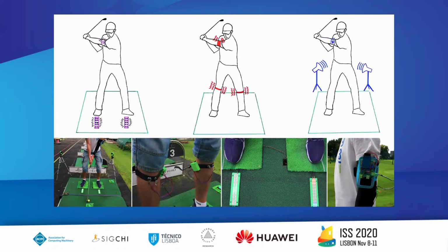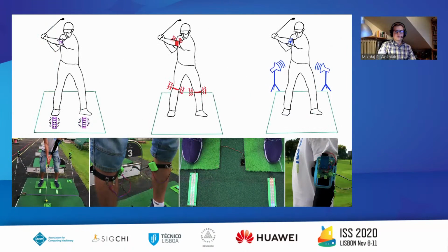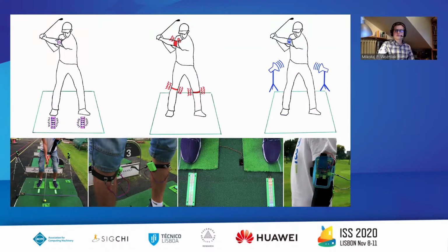We designed 3 different feedback modalities for Subtlety: audio, visual, and vibrotactile. Audio feedback used a frequency-based metaphor to indicate balance disruptions, similar to the one used in parking sensors. We used the near-field speaker arrangement to play the cues to the player. Visual feedback was provided using in situ LED displays and color coding, while vibrotactile stimuli were provided using wearable bands on players' calves.